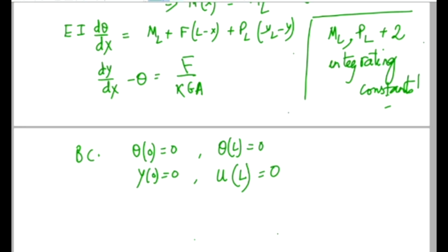And so we get 4 boundary conditions for the 4 unknowns. But neither Euler-Bernoulli nor Timoshenko beam theory allows axial deformation. So we need a theory which also allows axial deformation in order to solve these problems, right? Likewise, you see in both the theories, what can you see about the magnitude of rotation?